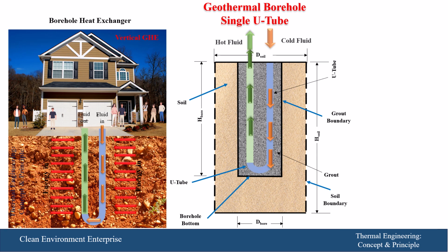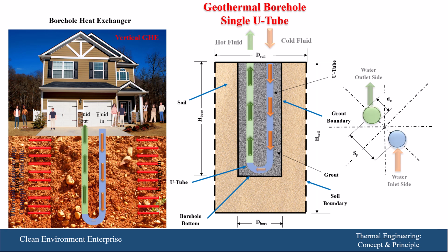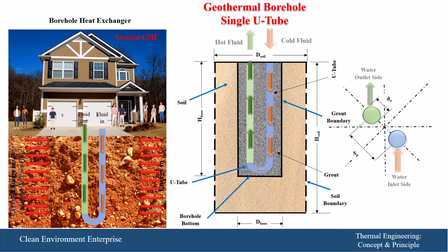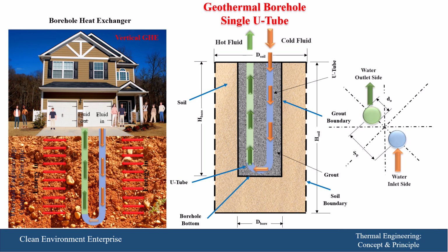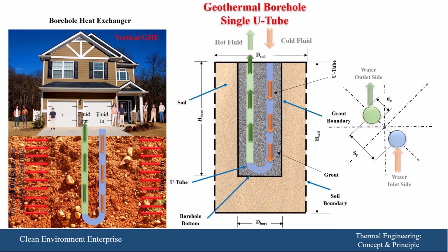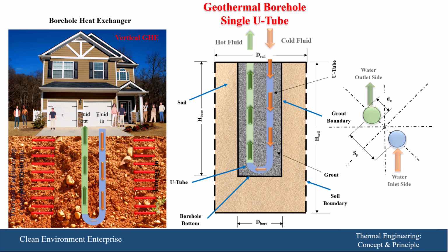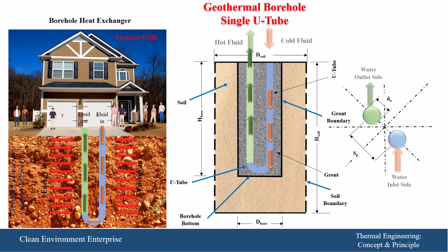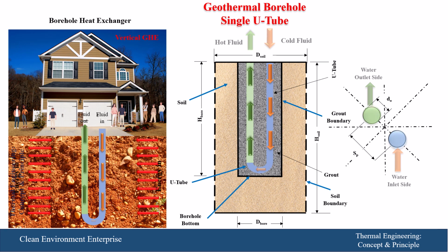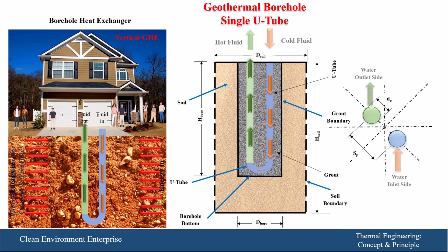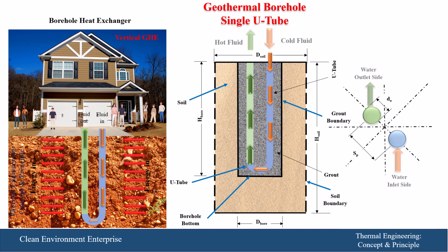So in that sense, we are extracting energy from the soil, which represents the earth structure, conducted to the grout, through the grout material, to the tube surface, all of that in conduction, and then by convection to the fluid which is passed inside that U-tube, and it could be water, shown in the right hand side photo, water inlet and water outlet.